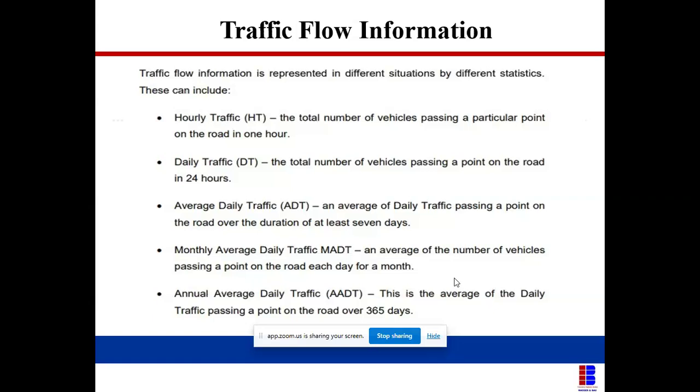That's why the starting point prescribed for the federal road, as stated in the federal manual, should be a carriageway of 7.3, which, based on research that has been carried out, can accommodate the average daily traffic and the annual daily traffic as well. It can accommodate more vehicles. So I see in most of our estate environments, most times the width of carriageway on most of the estates is sometimes 4 meters, 5 meters, because the traffic volume is also small. You enter your house, park, and go out. But in areas where you have more traffic volume, you see that the width of the road will be more expanded.